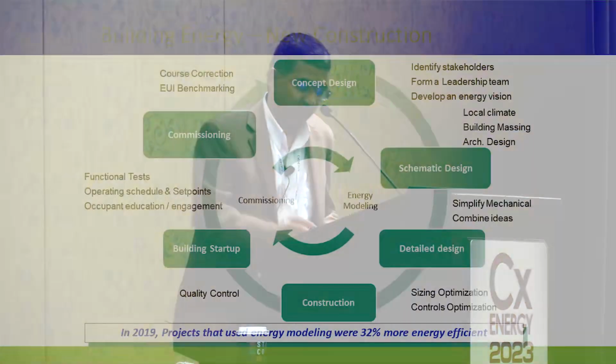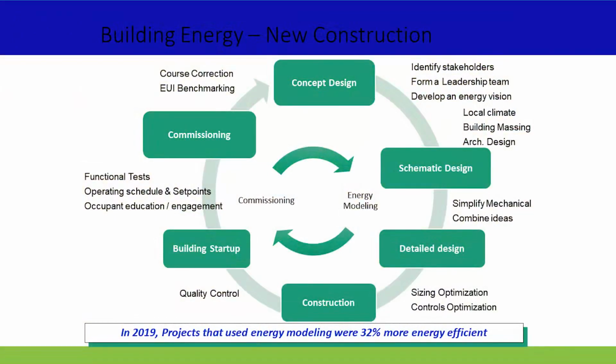But there are also lots and lots of small buildings that don't have enough money to do the retro commissioning. So we end up looking at their budget and doing what is called a light retro commissioning, because that's all they're looking for. It's an energy audit level 1, level 2, or level 3, those types of things. But the end goal is identifying, quantifying, prioritizing, and implementing savings opportunities.